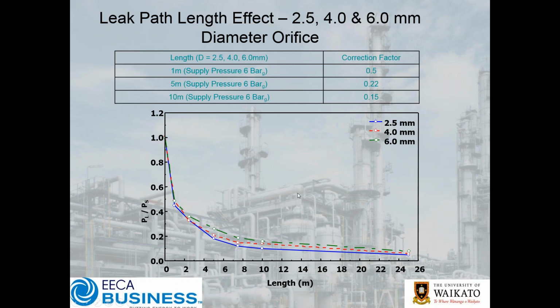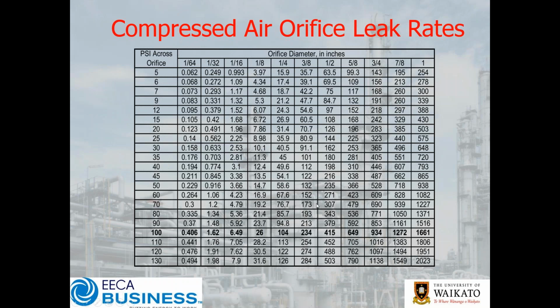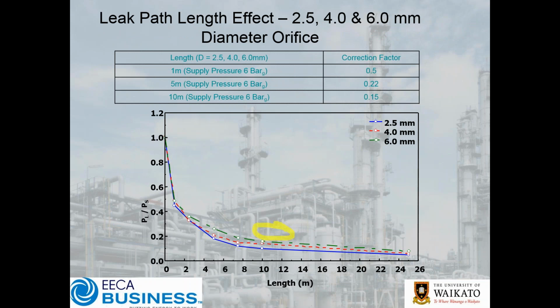So if we go back to our chart, if we grab our little highlighter here, okay, remember we were sort of in the middle here, at the 50 odd CFM. A 1 meter length tube is going to mean that actually that then drops to 25 CFM, and so where we thought we were at 100, we're actually only at 25. Okay, let me just erase that.